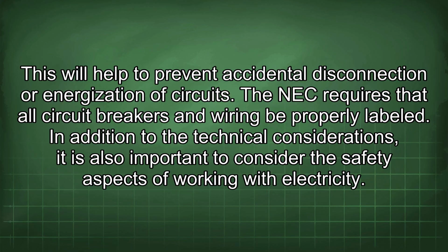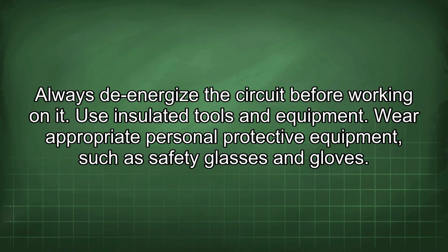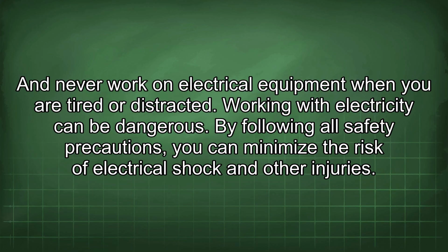In addition to the technical considerations, it is also important to consider the safety aspects of working with electricity. Always de-energize the circuit before working on it. Use insulated tools and equipment. Wear appropriate personal protective equipment, such as safety glasses and gloves. And never work on electrical equipment when you are tired or distracted. Working with electricity can be dangerous. By following all safety precautions, you can minimize the risk of electrical shock and other injuries.